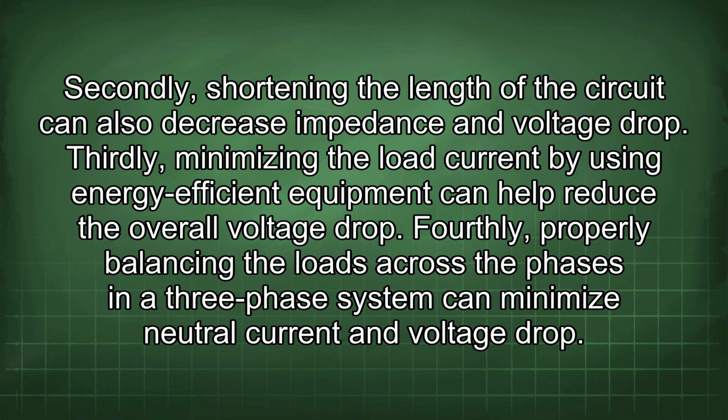Secondly, shortening the length of the circuit can also decrease impedance and voltage drop. Thirdly, minimizing the load current by using energy-efficient equipment can help reduce the overall voltage drop. Fourthly, properly balancing the loads across the phases in a three-phase system can minimize neutral current and voltage drop.